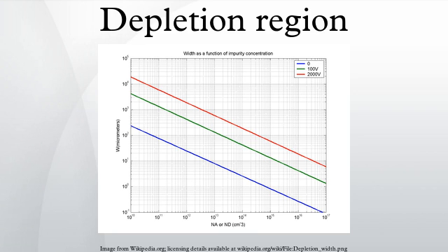Departure of an electron from the N side to the P side leaves a positive donor ion behind on the N side, and likewise the hole leaves a negative acceptor ion on the P side. Following transfer, the diffused electrons come into contact with holes on the P side and are eliminated by recombination. Likewise for the diffused holes on the N side. The net result is the diffused electrons and holes are gone, leaving behind the charged ions adjacent to the interface in a region with no mobile carriers.